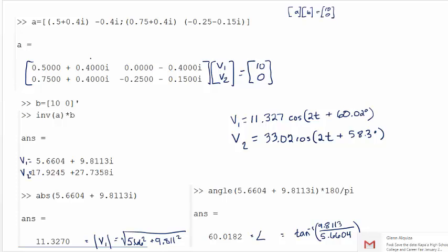So this is the matrix equation describing our two equations and two unknowns. This is just how you put it into MATLAB. That's the syntax for putting a matrix into MATLAB. B has to have this little symbol for being transposed, because B equals this, right? So it's in that direction. It's a column vector. It's called a column vector.